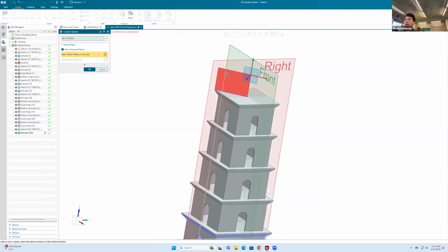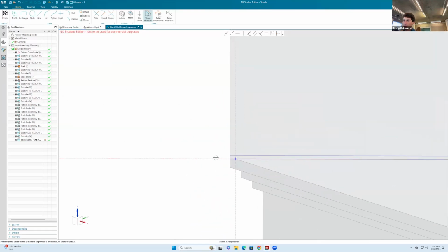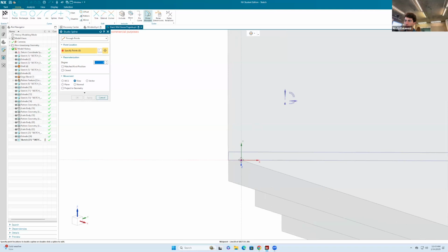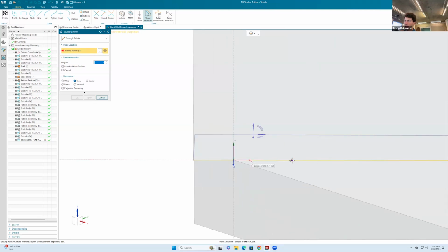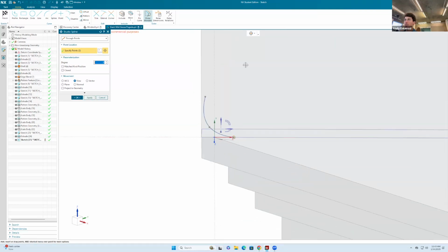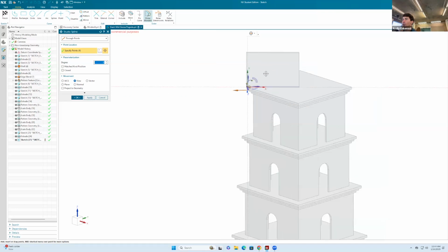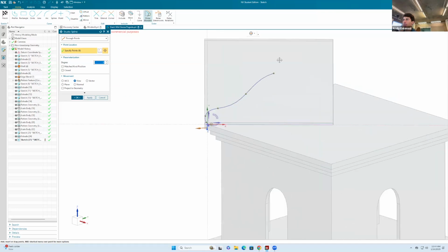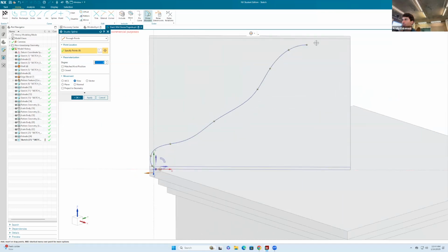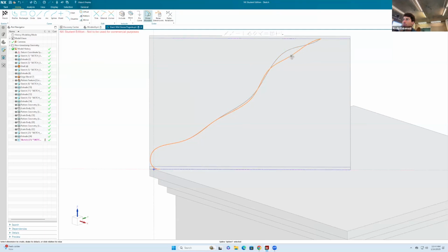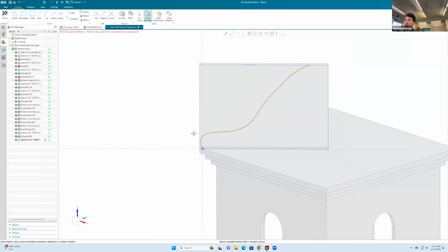And now we'll go here to sketch. Here, sketching that face. And we're gonna bring our friend the spline tool to make a kind of a nice looking organic shape that I'll probably not be very satisfied with, but it doesn't matter. I'll say okay. I can make it look something like that.